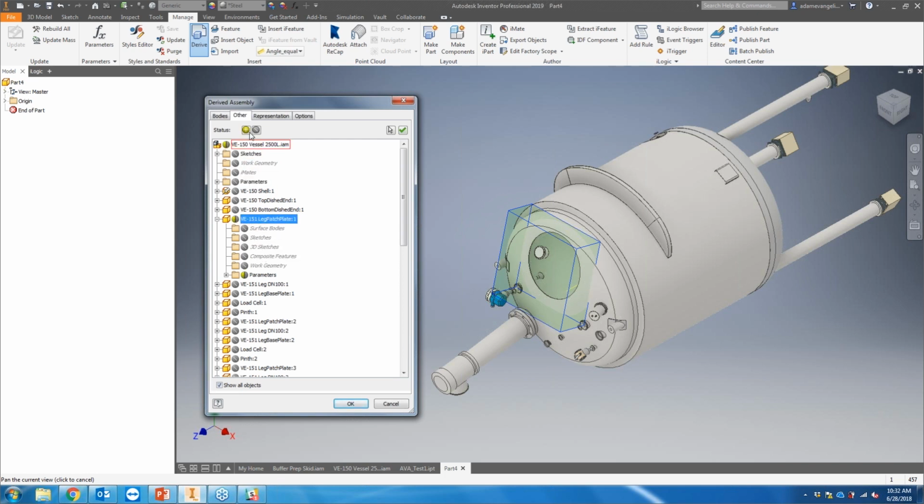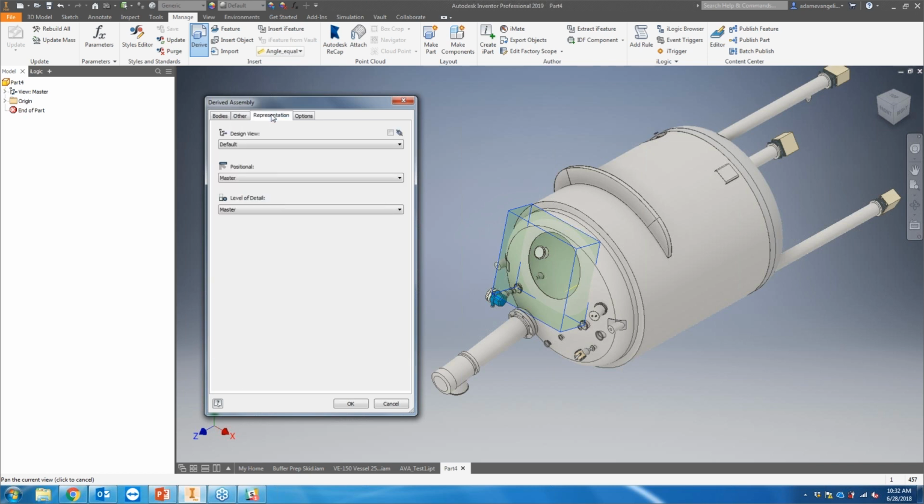And notice there's only 2 options here for include and exclude. So if I want to include surface bodies or not include this stuff over here, I have that option too. And so this really speaks to the point of derived part, in that you could bring over old references that you're using in the original assembly. You could do some more Boolean operations to tailor the derived part a bit more. It's going to be a better springboard for you to make new parts from this, as opposed to just making a simpler reference a la Shrinkwrap, right? But kind of an interesting point to make.